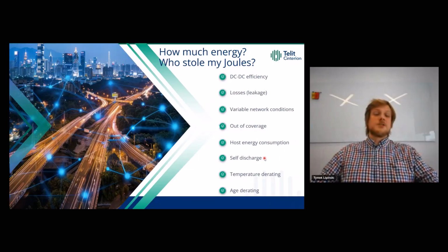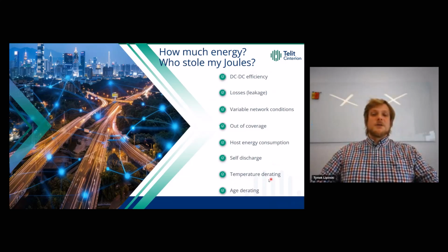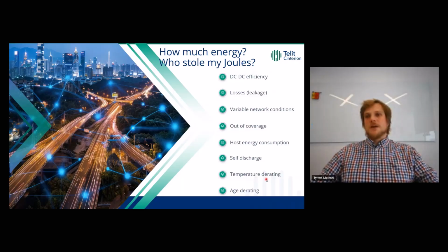We have to factor in the self-discharge of our battery because every single battery will self-discharge. That's why they have a shelf life. We have to factor in temperature derating. Every component will behave differently at a set temperature, especially capacitors and diodes: their characteristics will change and their leakage current will change with the temperature. Same goes for age derating. For every single component, we have to factor that in because age has a big role to play in designing devices to be launched with a single battery for 5 years into the field.